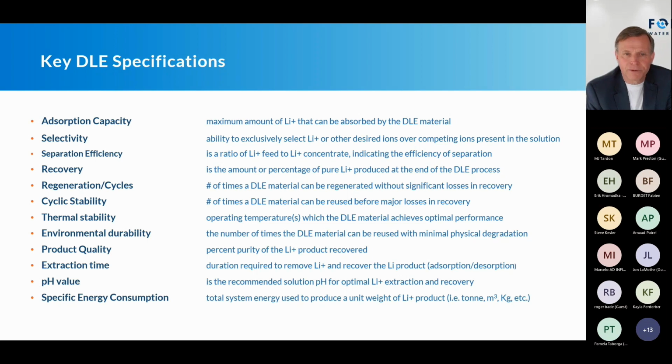Some DLE providers like this and some don't, but have it pulverized and crushed and sent out for analysis and have those microcontaminants analyzed. Because if you see those microcontaminants, they're not going to go away. They're going to continue to load up on the material. So just a quick trick: take the material, crush it, send it out for analysis and see what type of microcontaminants have loaded up on it. Because after 1 year, 5 years, 10 years, it may be a lot.